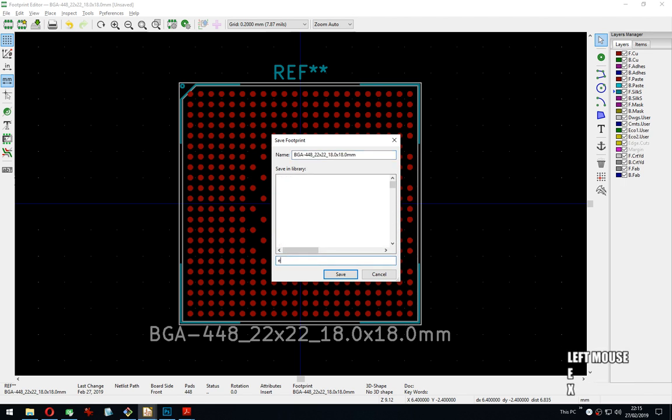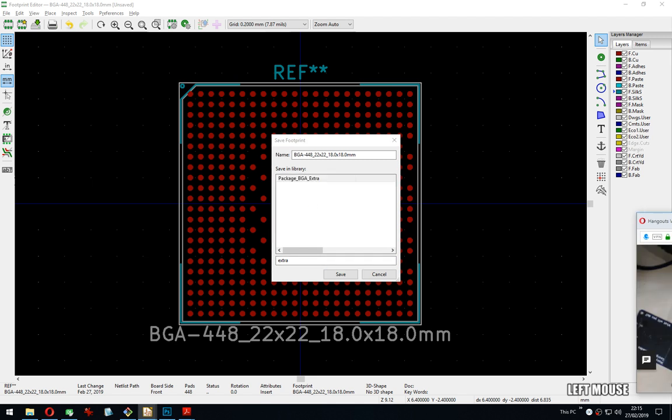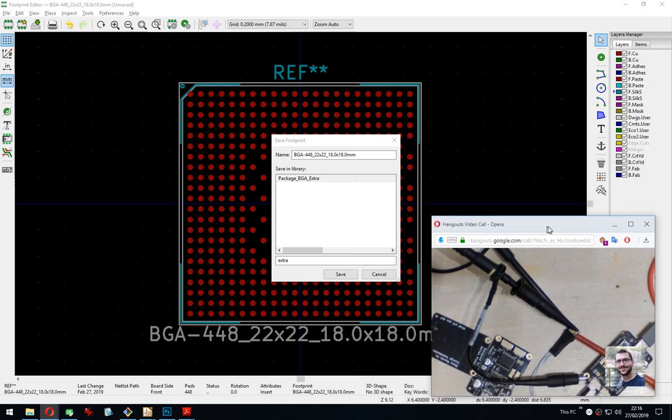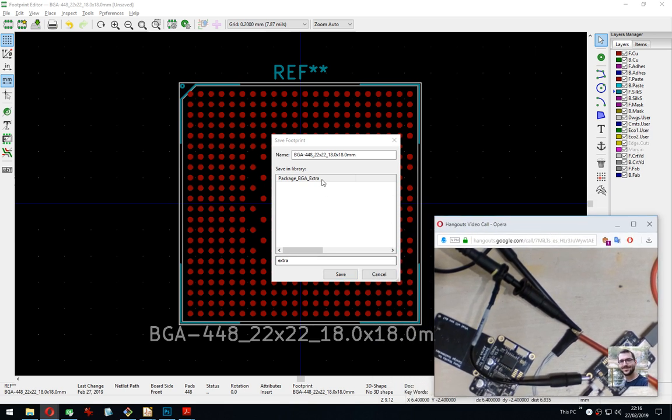Oh crap. There we go. Yeah, I figured out why the CAN device never went up, because I didn't power the transceiver, and now I powered it. Now it just goes up without problem. So nice. Yeah, that's something.